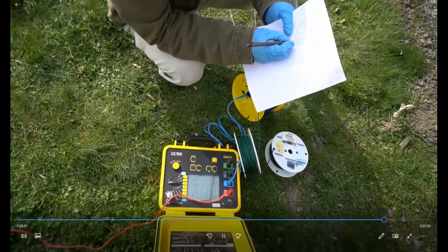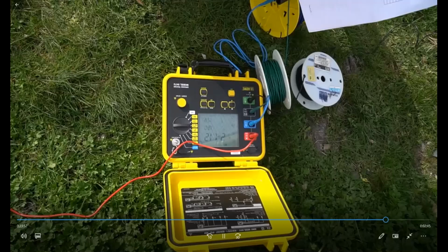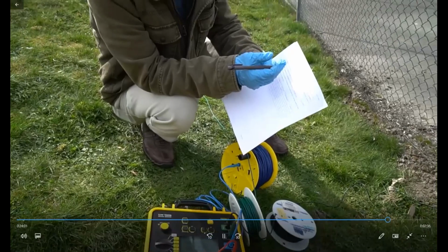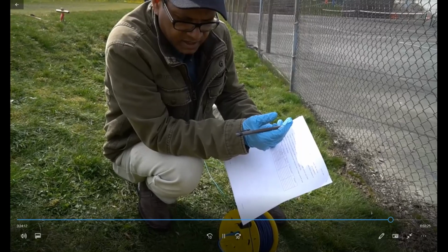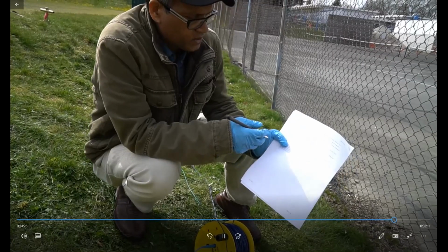So this resistance is 21.12 ohms. Okay, so the same way we will collect some other data for the step potential, and that will be the final table of data for lab number 3. And definitely I will provide you with all the data we are collecting here with William, and you will have to prepare your report, and how you will do that I will discuss in our lecture class. Okay, so for now we are almost done.